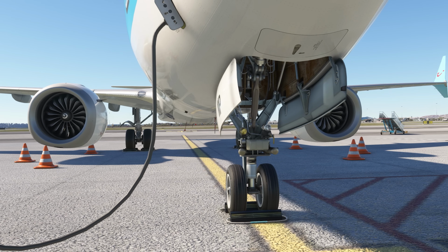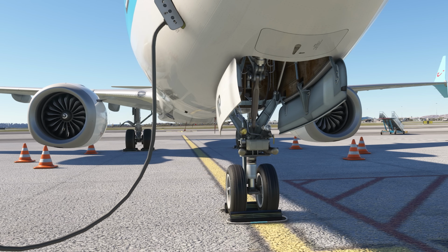So the first thing I wanted to point out whilst we're outside here is the nose gear. It's actually been extended a little bit in comparison to the NG by about 8 to 9 inches, and that's to accommodate these huge CFM LEAP 1B engines, which have a massive 69-inch fan. You actually notice this during the walkaround. You don't have to duck as much to get into the nose wheel when you're inspecting the nose gear there. So that's one of the major changes at the front here.